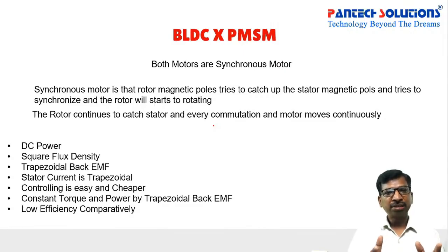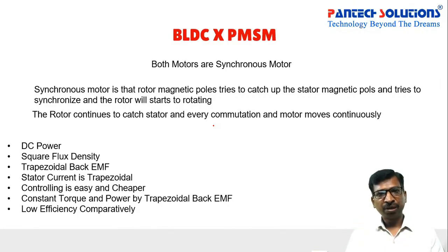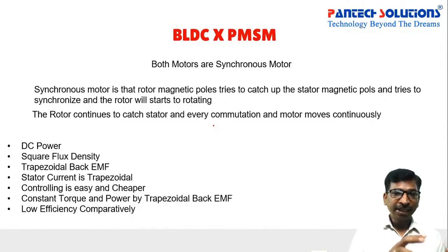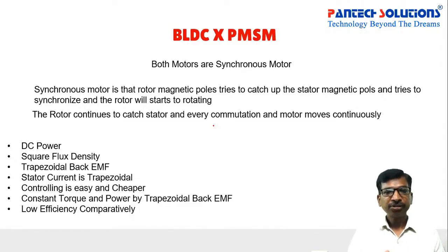I mean, I'm not saying the BLDC motor has entire difficulties and all. See here, if you compare BLDC and PMSM, comparatively PMSM has lower harmonics, but BLDC has higher harmonics. But if you compare with the DC motor, BLDC will be the best one. And if you compare with the PMSM, PMSM will be the best one. Again, it depends on your application where you are going to use this motor. So it depends on the target application, then machines can be categorized by the optimal solutions.